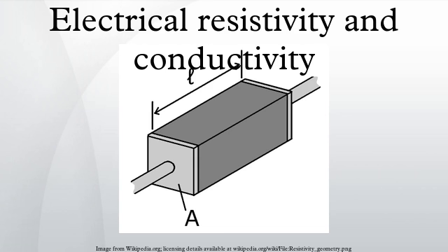Semiconductors. In general, resistivity of intrinsic semiconductors decreases with increasing temperature. The electrons are bumped to the conduction energy band by thermal energy, where they flow freely and in doing so leave behind holes in the valence band which also flow freely. The electric resistance of a typical intrinsic semiconductor decreases exponentially with the temperature.